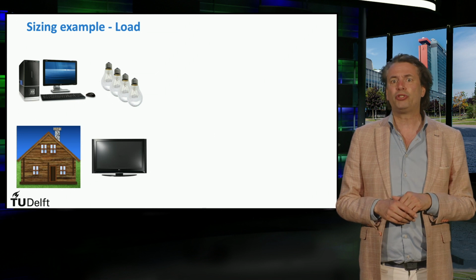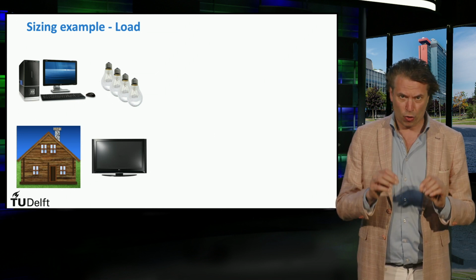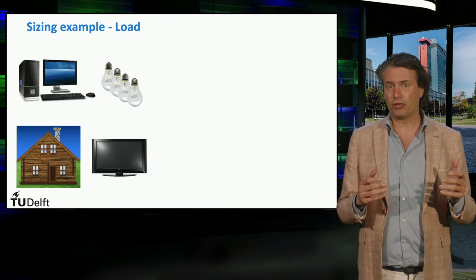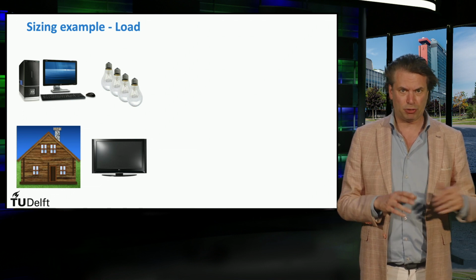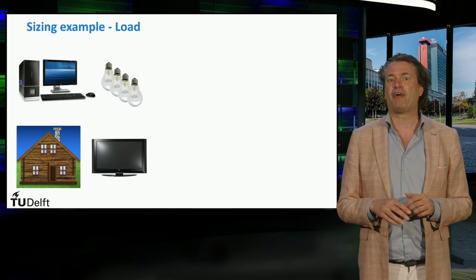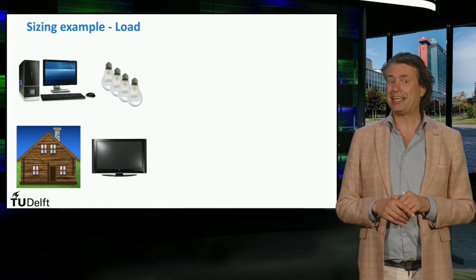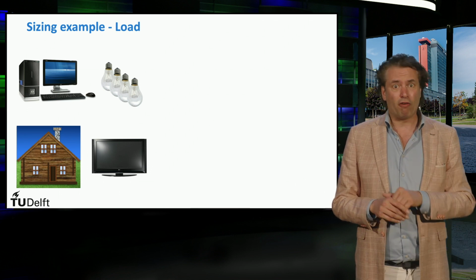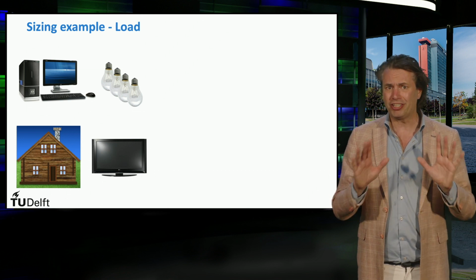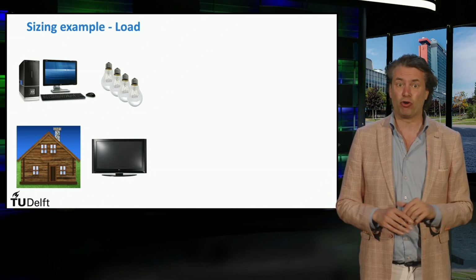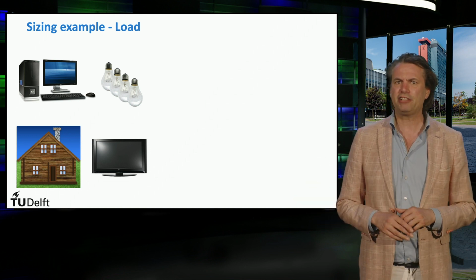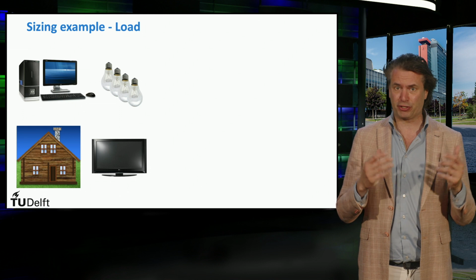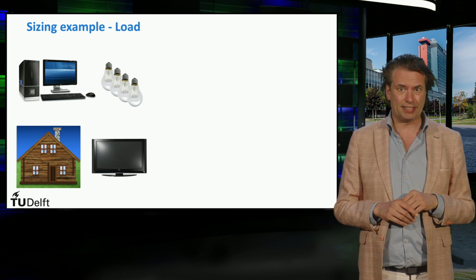These include the use of a simplified load profile and disregarding the location's meteorological effects like ambient temperature and wind speed. Moreover, for the simplified design, we simply use the standard test conditions data of the PV modules and therefore do not take into account the sun position or PV module orientation. In this video, you are going to learn about the different steps involved in this design strategy.